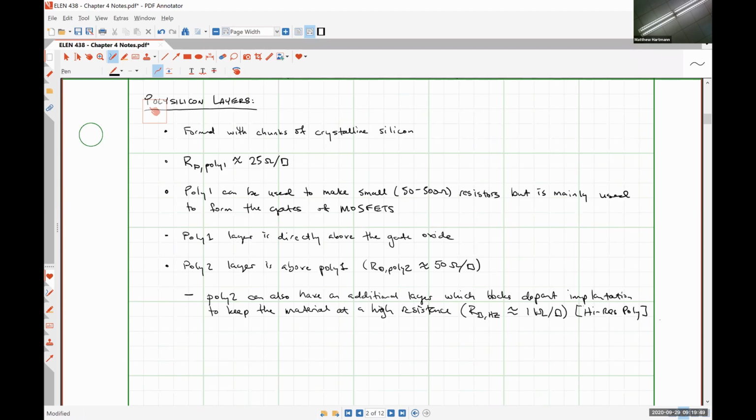Then we're actually going to get to start talking about transistors and all that kind of good stuff as well, and some schemes on how to minimize their footprint while achieving the particular width-length ratios that we need, because hopefully all of you guys remember from your analog electronics classes that, say, the drain current is directly proportional to the ratio of the width divided by the length in a transistor, but sometimes we don't have the physical footprint necessary, so we can do things like fold them or other things like that to help us achieve the specific characteristics we're looking for.